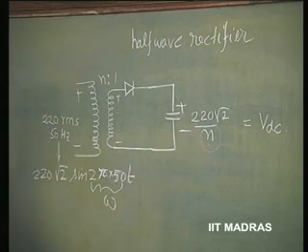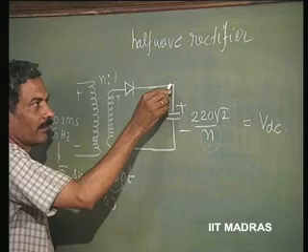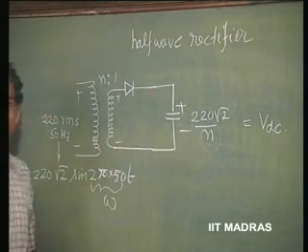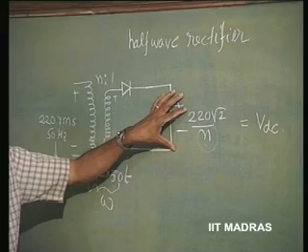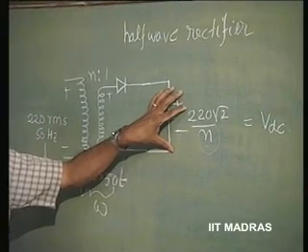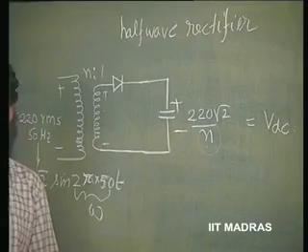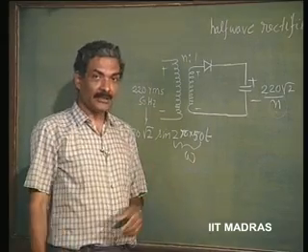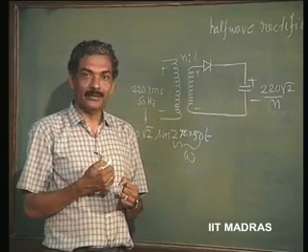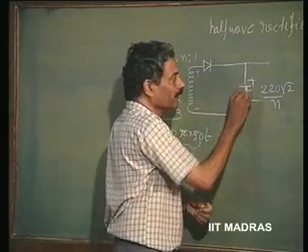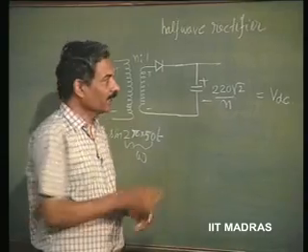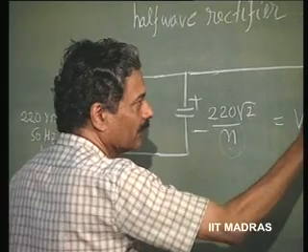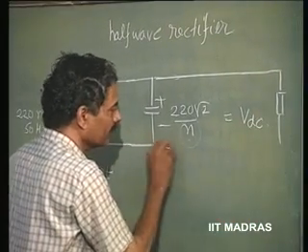Half wave because, right, if now we put a resistance across this, which is likely to take place, because we cannot retain this voltage forever like this. In an ideal capacitor it is true, in an ordinary capacitor there will be some leakage resistance across the capacitor. In a practical situation we would like to draw the current from the battery, in which case the capacitor has to deliver the current and the capacitor will discharge, and therefore, the load for the capacitor is always going to be represented